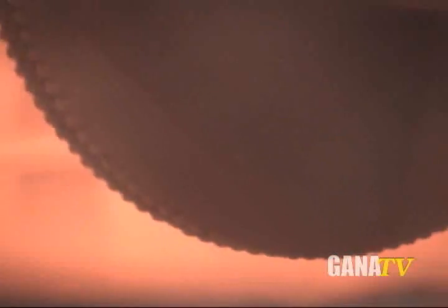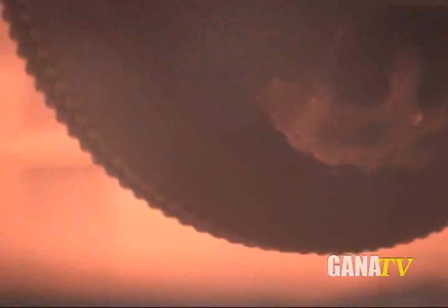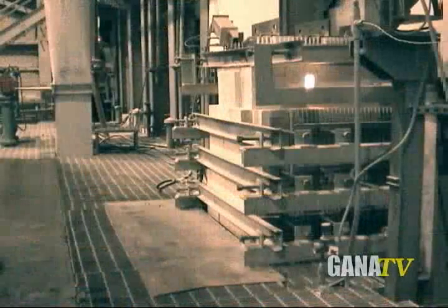The glass, now known as the ribbon, spreads out onto the flatness of the tin, leaving the upper and lower surfaces of the glass perfectly flat and parallel. This flowing process makes the glass thicker by confining its initial outward spread over the tin. To make the glass thinner, top rollers pull the glass along the line, speeding up the flow and creating a gentle stretching effect. A controlled atmosphere consisting of hydrogen and nitrogen within the bath chamber prevents the tin from oxidizing.